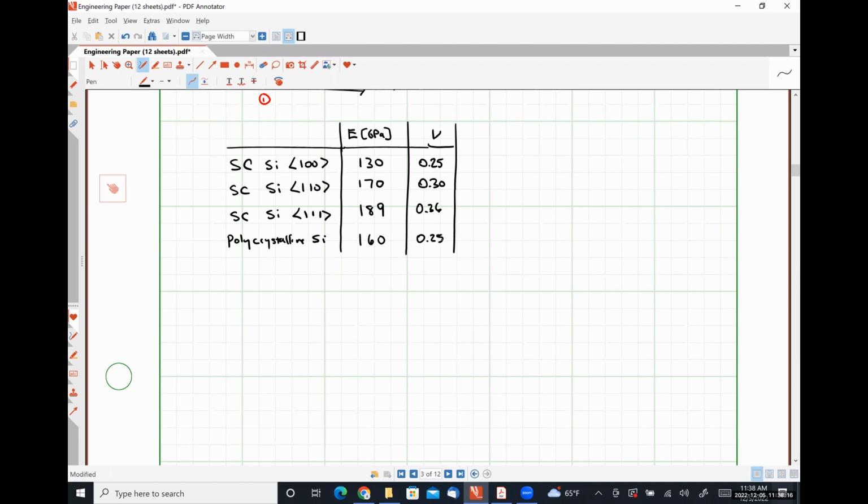Okay, they'll also have different fracture strengths, but the range on that is so big that it's arguably not worth giving some median value, because we're talking about the difference between 0.7 gigapascals and 7 gigapascals. It's a full 10-fold order of magnitude that it's going to fall somewhere within that range.